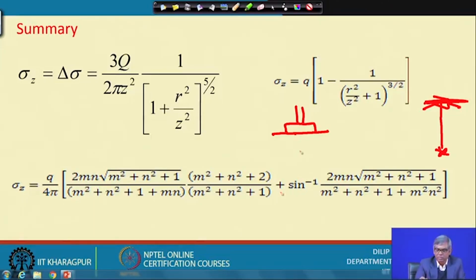So, you need to find out at different depth what is the pressure because of this extra foundation load, and that actually you can find out by different methods. There is a Boussinesq's point load formula we have mentioned, and though Boussinesq gave the equation for point load, in practice hardly any have any point load. Most of the time we apply load through area, and to use this point load, actually if there is an area loaded with some intensity, I can consider the entire load is acting at a center, and then point load formula can be utilized.